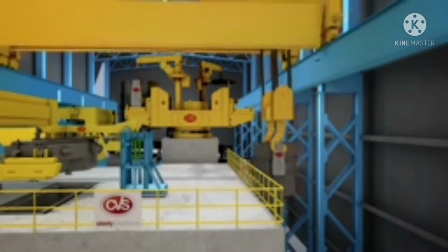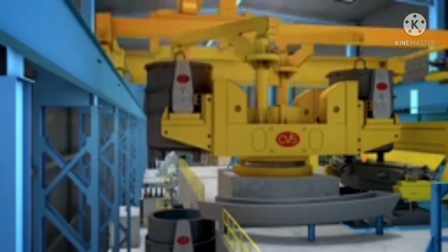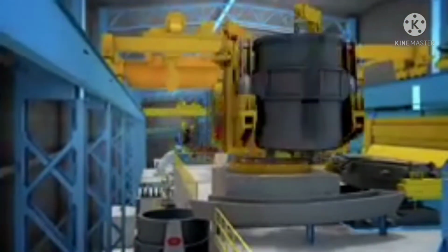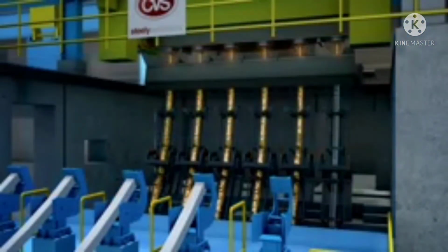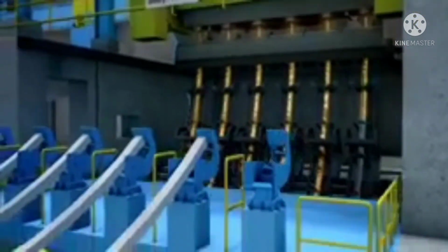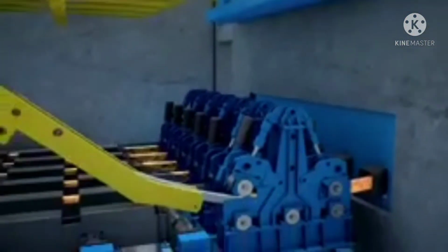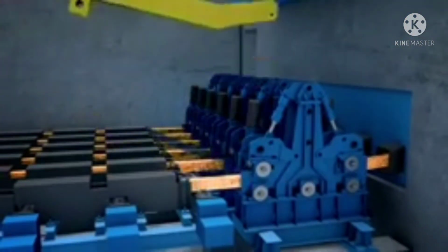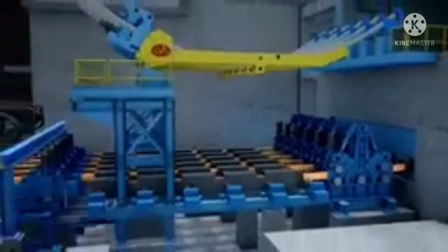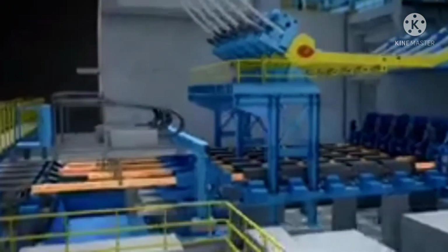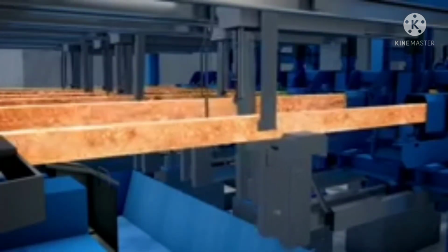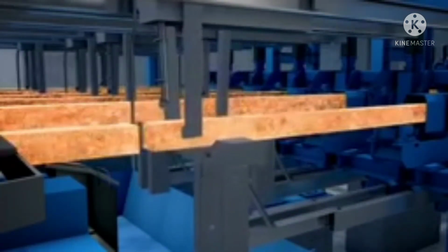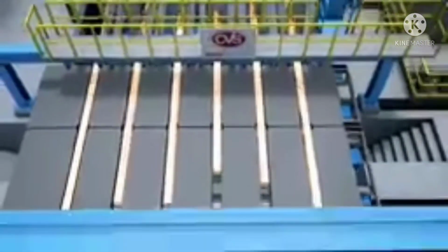The next step is to pour it into cold molds. This causes the metal to cool quickly. Once cold, the metal is then cut into desired lengths. Depending upon the application, slabs for plates, blooms for sections such as beams, and billets for longer products such as wiring or thin pipes.